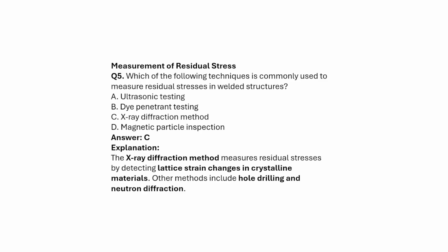Some other methods are also there, like ultrasonic and X-ray diffraction. If you do XRD and residual stresses are there, the peaks will be shifted from the exact location.